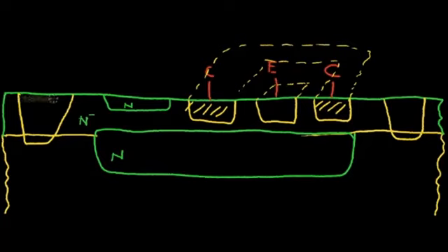So this region here is a P material, and I forgot to, let me change pens here. When this P region is put in, I'm going to put a little P region into this isolation area that I forgot to do. So let's add that in. That gives me a little better contact to this isolation region.